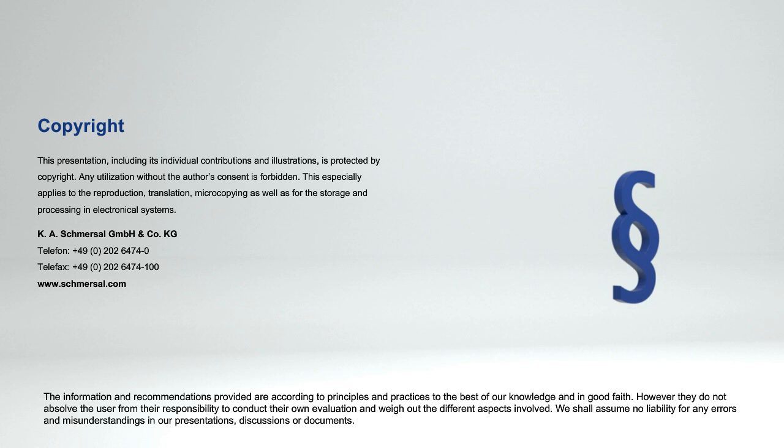So you can see that in there, but that becomes one number of your overall safety function that you're adding into it. So you're looking at the performance level of that safety function, not just the individual components. You can get a component that claims a performance level because it can achieve up to that performance level. But it's the combination of how it's installed into the safety function, looking at the overall safety function, that you're trying to achieve an overall performance level for.